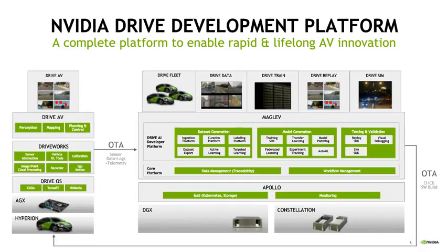Constellation is our embedded SoC AGX, running in a racked-up version in the cloud so that we can do hardware-in-the-loop simulation of our stack. I'll come back to that later. This is a really important aspect of this platform. Constellation enables us to validate our AV software just as if it was running on the real car, except it's in the cloud.